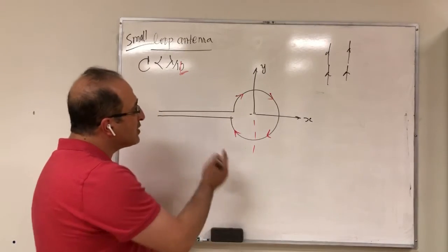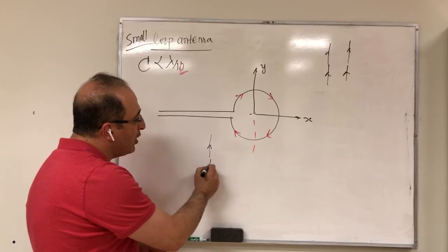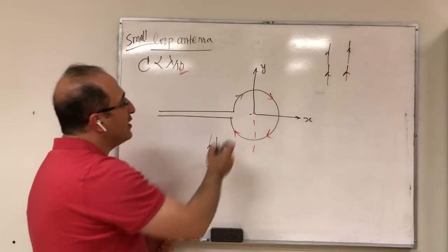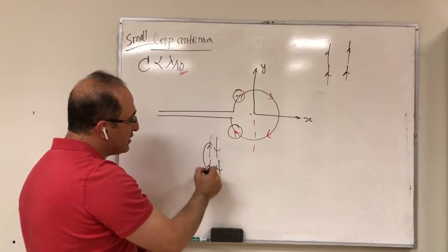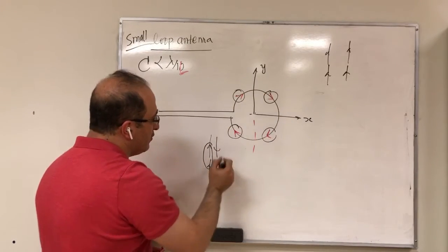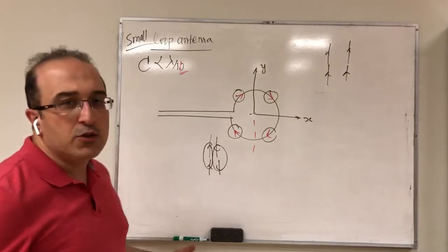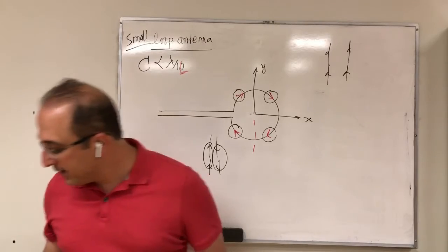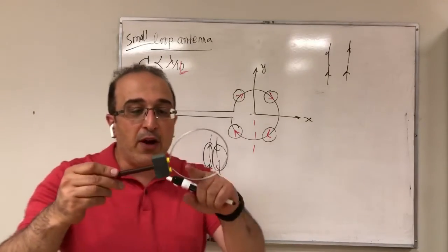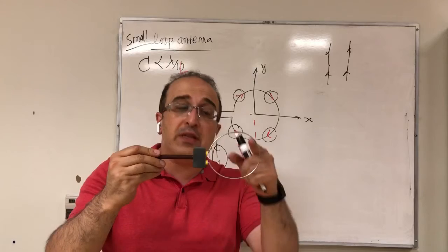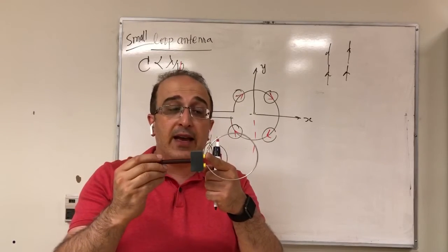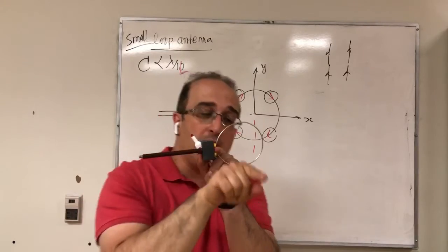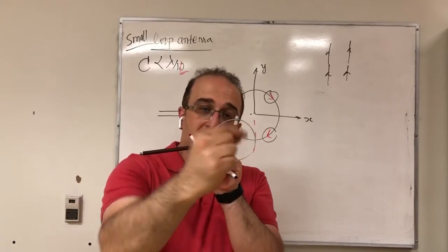And you could also justify it based on these two dipoles that are essentially exactly opposite. So that's the justification that there is no radiation here. Now, that essentially means if I work at a frequency where this loop is small, let's say lambda by 10, then I'm not going to have any radiation toward you, so toward the axis of the loop.